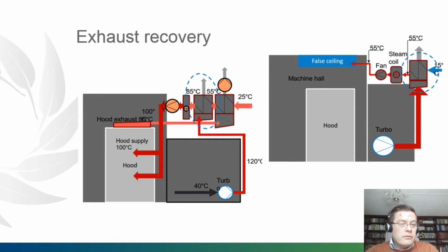This heat is created as a result of compression in a turbo blower. We can roughly say that if 1 megawatt is taken from the network, half of that, about 500 kilowatts, can be recovered back to the process use. This can be direct use for the drying hood makeup air system or with a separate heat exchanger for other usage like warm water. In some cases, even a direct blow under the hood can be a highly efficient and low-cost solution.